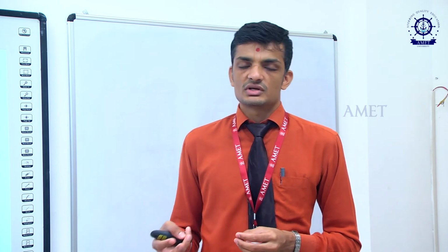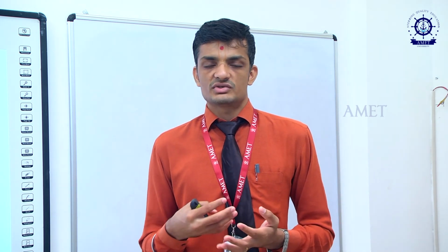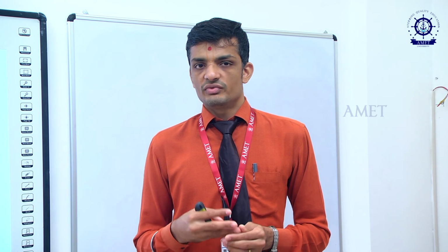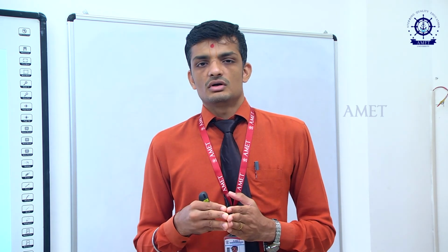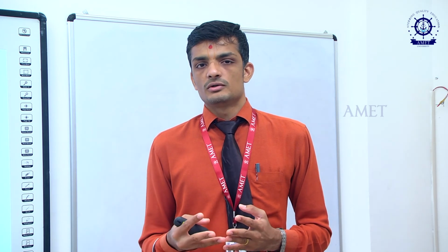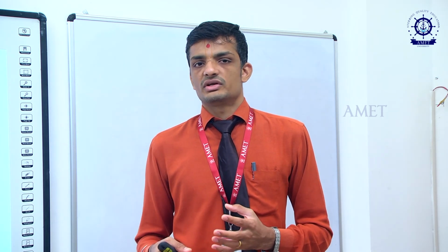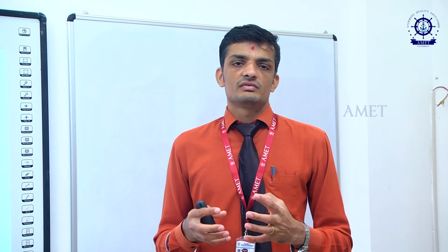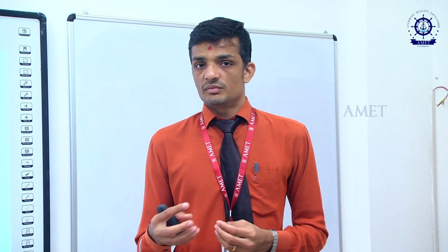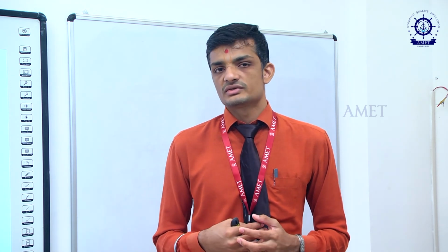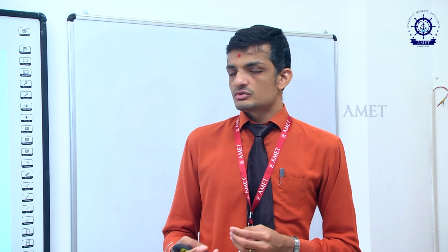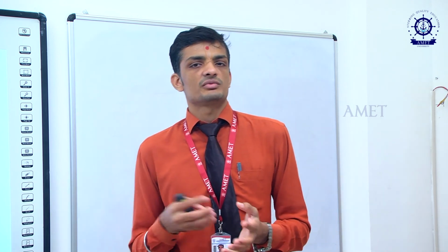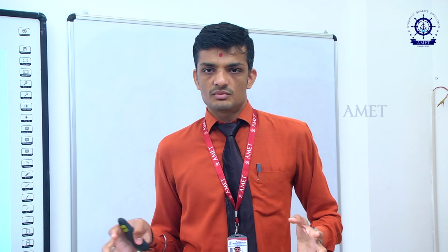Once you get the shape functions, before starting the analysis, you should know the governing equation, that is, the mathematical model. So we use energy methods and other methods, weighted residual methods, to break down that mathematical model into a matrix equation. That we call the element equations. From those element equations we will get something called the stiffness matrix. So one must know what the stiffness matrix is for a given problem. If it is a hybrid problem where 1D and 2D problems are mixed together, then the matrix becomes a hybrid. You have to club everything together.